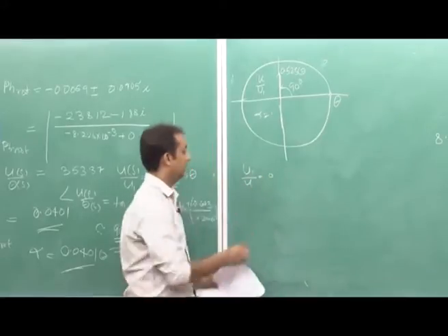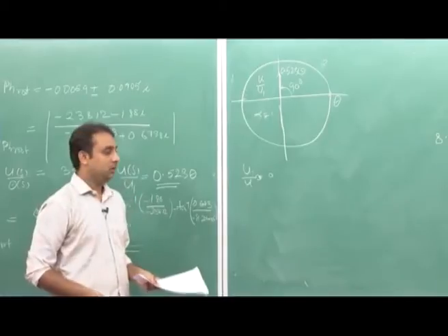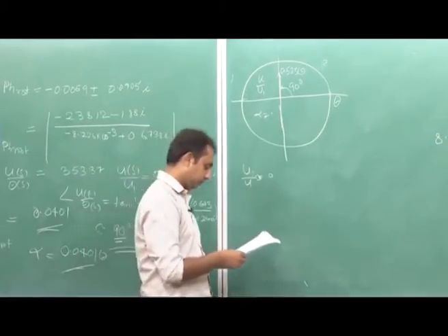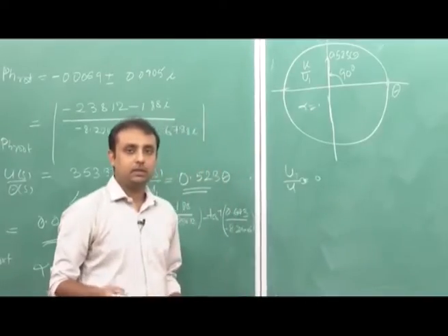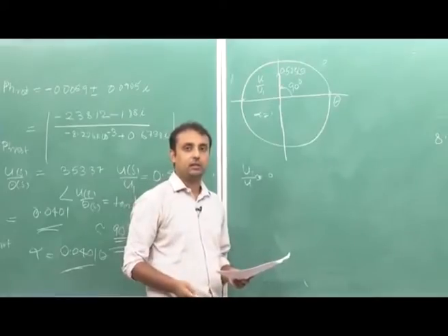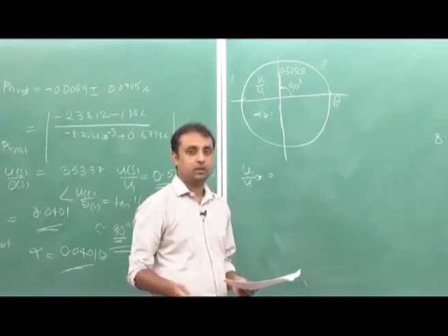So while approximating short period mode, your velocity or speed remains constant. From the analysis, we can see that the short period mode takes place at constant speed, while phugoid mode takes place at constant angle of attack.